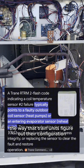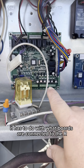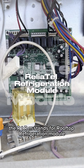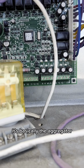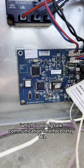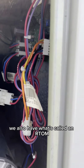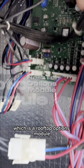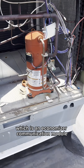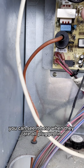And if you know the way that Trane units figure out their configuration, it has to do with what boards are connected to the RTRM, right? The RTRM stands for Rooftop Refrigeration Module. It's basically the aggregator of everything that's in this unit. So in here, we have an LCIR, which is a LAN Talk Communication Interface ReliaTel. We also have what's called an RTOM, which is a Rooftop Options Module. There's also an ECA, which is an Economizer Communication Module, and the Ignition Module is also part of that intermodule communication. You can see it here.